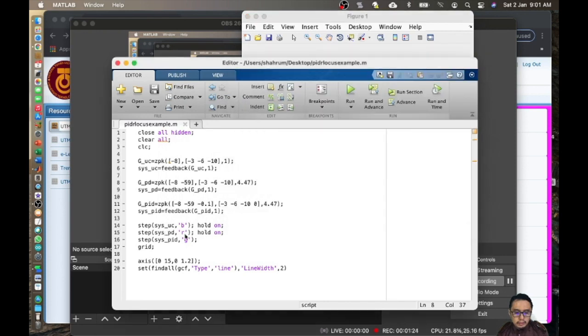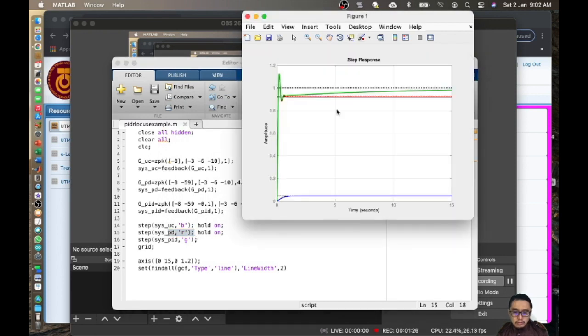Okay, that's the PD. So you can see that the response has less steady state error, but better peak time. Okay, peak time is 0. We require it to be 0.21 if I'm not mistaken. And then for the case when we use the 0.1, this is what we achieve. Okay, the steady state error is almost 0.